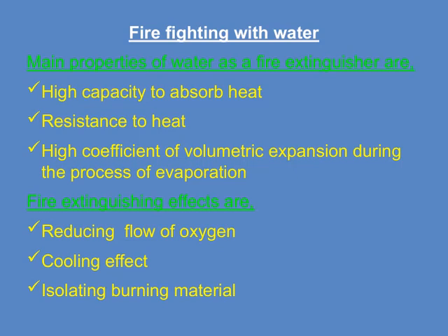Firefighting with water relies on some key properties that make it such an effective extinguisher. First, water has a high capacity to absorb heat, which means it can really help in lowering the temperature of the burning material quickly. It also has excellent resistance to heat itself, so it doesn't break down easily when exposed to high temperatures. Another important property is its high coefficient of volumetric expansion during evaporation, which allows it to absorb a lot of heat as it turns into vapor. Now, these properties translate into effective fire extinguishing effects.